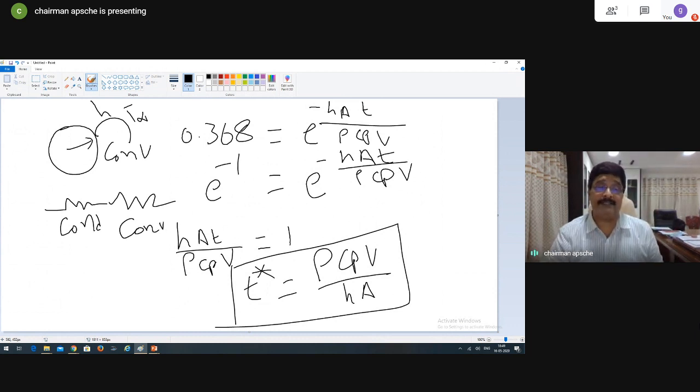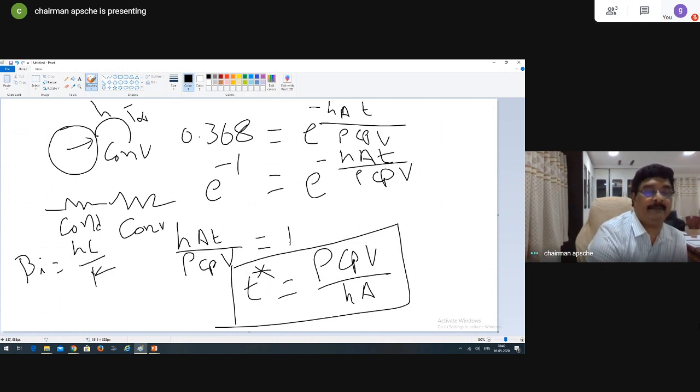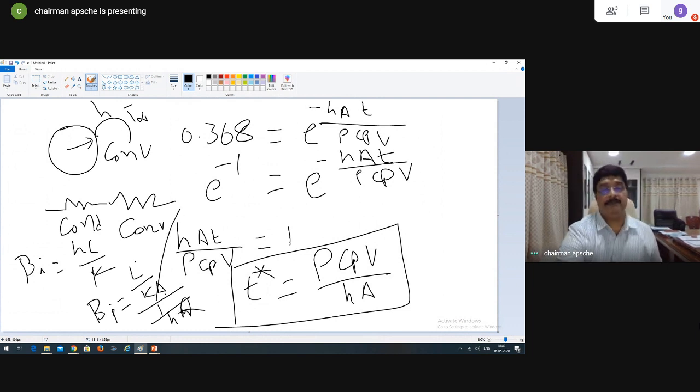Now, what does the Biot number tell us? The Biot number compares the conduction resistance to the convection resistance. The Biot number is equal to hL by k. What did I say? The Biot number is equal to L by kA divided by 1 by hA. So A cancels, and h goes to the top, so it is hL by k. Here L is the characteristic dimension, do not get confused by that either: L is volume divided by surface area, we have covered that too.